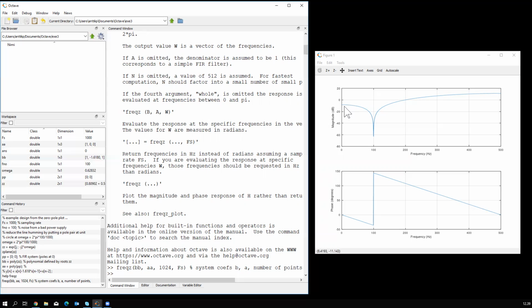What I can actually do is move the pole a little bit off the 0, for example, put poles closer to the unit circle, so that I can get more gain near 0 frequency. I can also try something fancy here and try to get an almost flat passband, but sometimes it works, sometimes it doesn't.